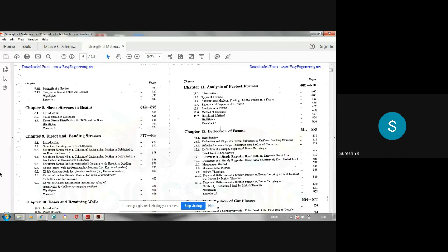RB is 5, sir. No, what did you say before? 13, right? Check whether 13 is correct. Minus 10 into 2 plus RB into 5 minus 15 into 3 is equal to 0. Then RB is 13, sir. Correct. 13 and RA 12, 25 minus 13. Correct.